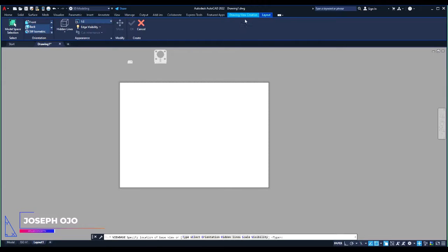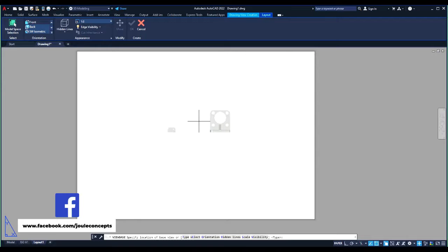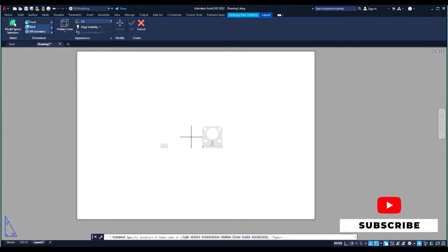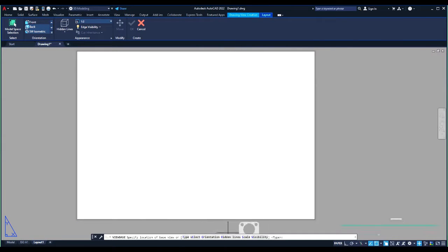So that's the first thing you notice. The second thing you notice is that you have two shapes. You notice in the model we had two shapes. So AutoCAD doesn't seem to know which one it should bring into this draft or which one we want to get the draft from, so it's bringing both of them. But there are options down here that can help change that. So let's assume I want to change. I don't want to bring the two drawings or the two models. I just want to bring the one on my right, which is here.